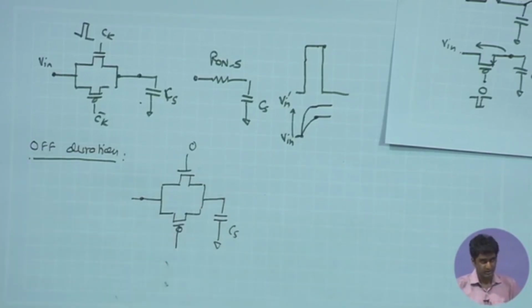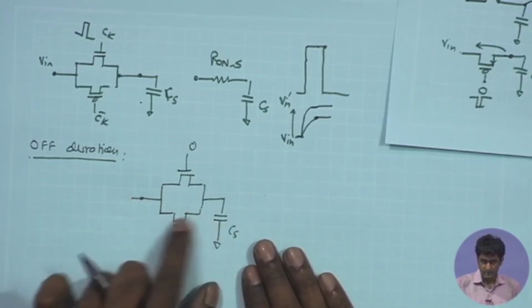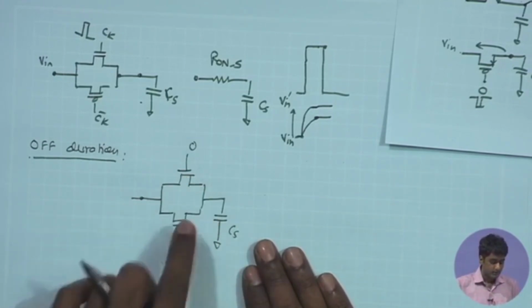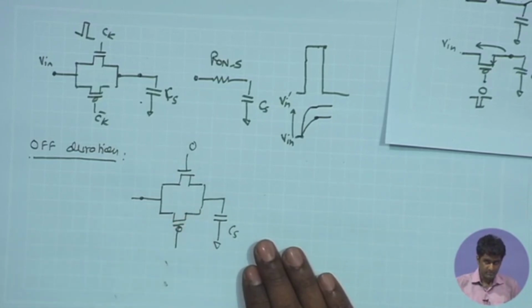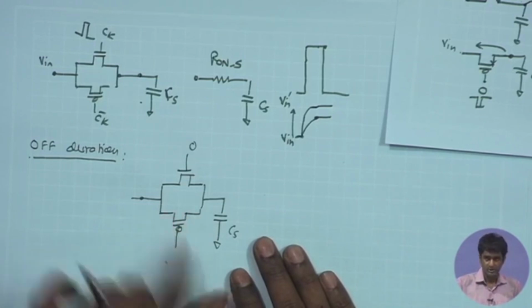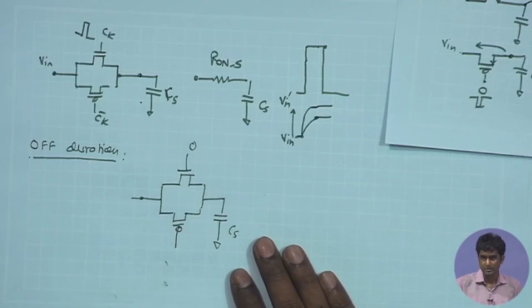If we talk about say 180 nanometer CMOS technology which we are using in our simulations, there the subthreshold leakage will still be relatively small, gate to substrate leakage is yet smaller. However, the reverse bias junction leakage can be pretty significant, and that is something which also increases proportionally with the W of the transistor. So, the subthreshold leakage for example can be reduced if we are having longer channel length, that imparts a relatively longer channel behavior to the MOSFET, and that can reduce the subthreshold leakage current. But if we are looking at the junction leakage for example,